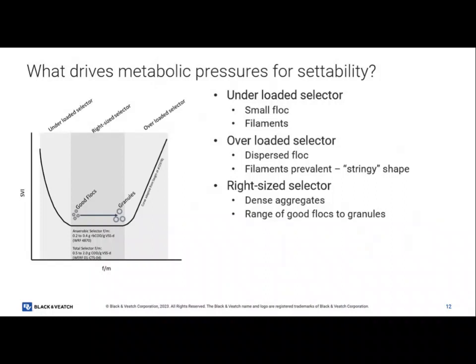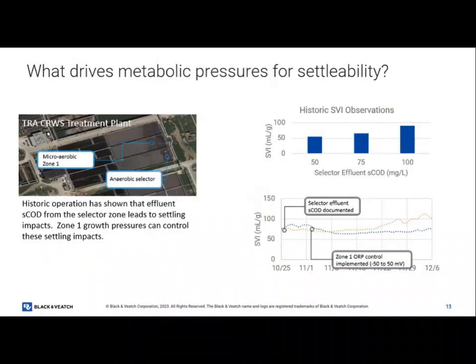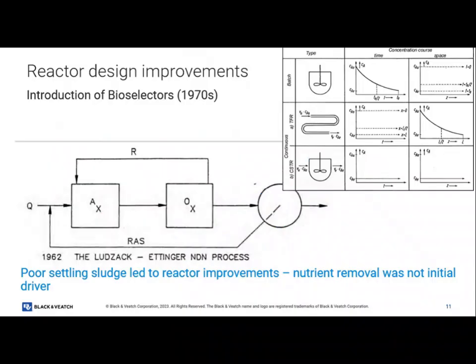Not a lot of plants have that ability. That's pretty unique. I think Benton Creek has it, Wilson Creek, and he's said they're getting it at Mountain Creek. That's a pretty rare one. The only other thing you can really do, some facilities have step feed. If it's too high, like if you're way out here, you can step feed it down the basin to change that up or down.